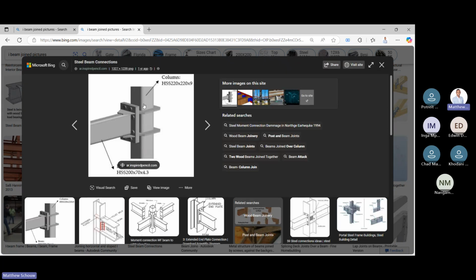There's also a whole module on bolt design and whole standards based on that, on how to design bolts and what the correct size of bolts is, because bolts experience tension, shear, and bearing or crushing stress. A person in civil or steel structural design really focuses on this, but as engineers we also have to build structures. So this is just a quick one.